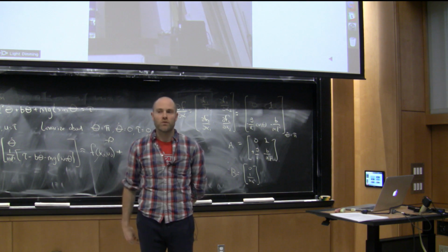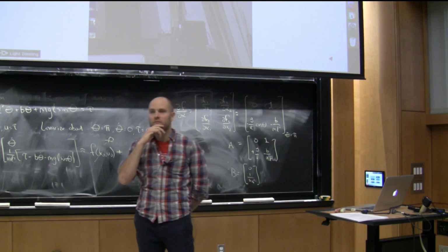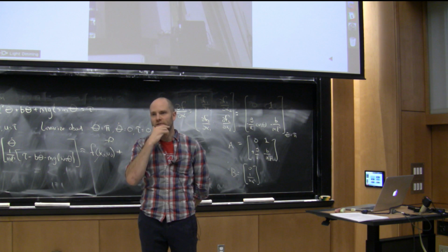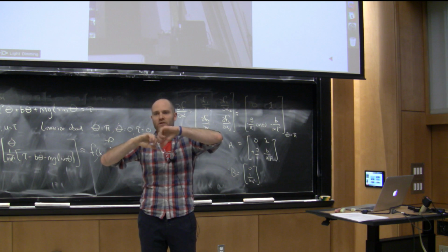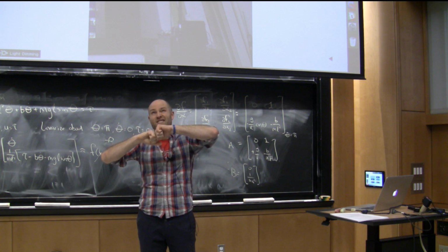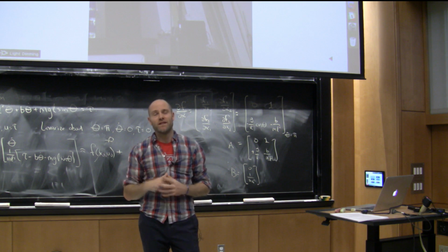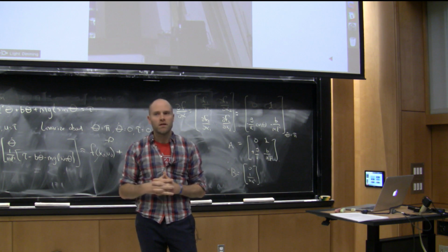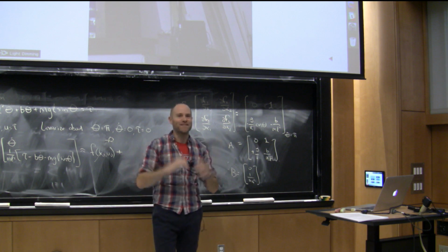Once you have an electric motor in there, do you have issues with static friction in the motor and minimum torques? Yeah, I lumped that into the backlash, but it's really a combination of backlash and static friction. It really looks the same. Especially because it's this torque drive actuator, backlash really is static friction mechanically, whether it's coming from the actual motor or the transmission. I'm guessing it's more the transmission, but we had enough money to get the Maxon motors, so those are pretty good.